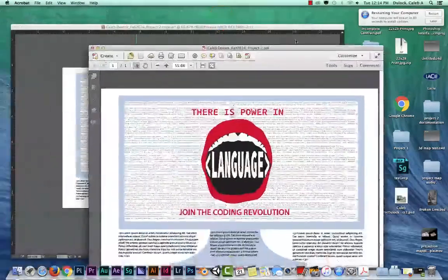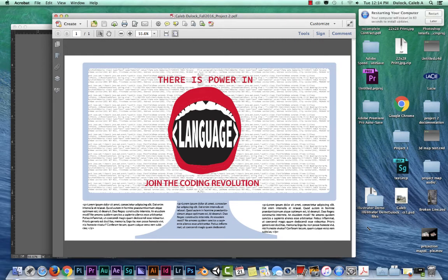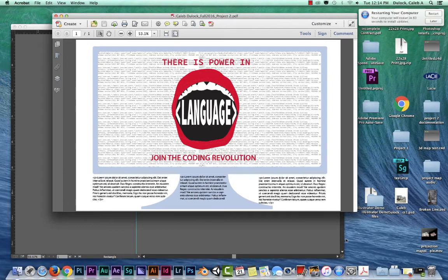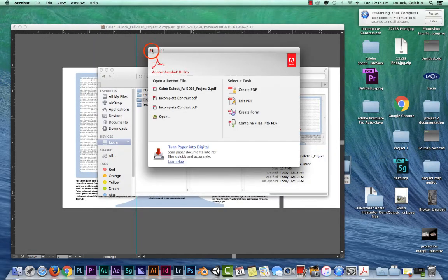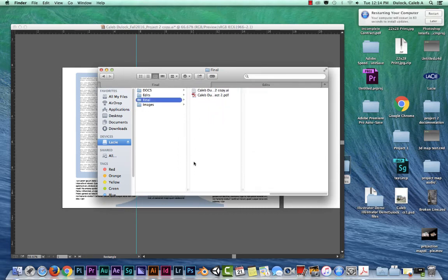All right. Judging by the file that it pulled up in front of me right now, it looks like everything came out correctly. My PDF looks good, my text looks appropriate, nothing is converted incorrectly, and there are no random graphics showing up in my PDF file. This is important. So there you have it. That is how you create your final formats from Adobe Illustrator.